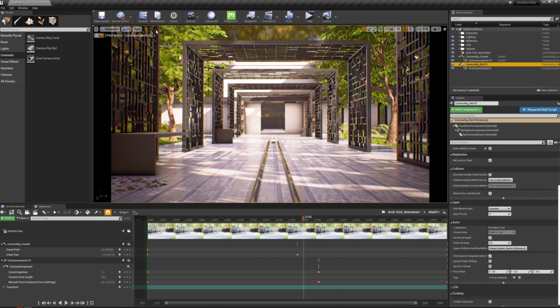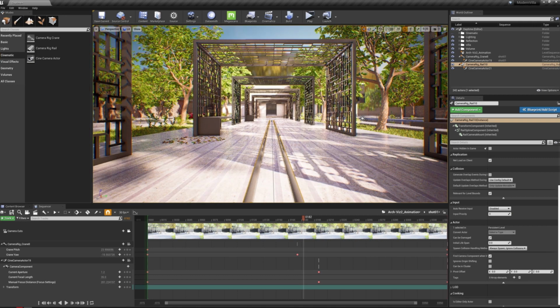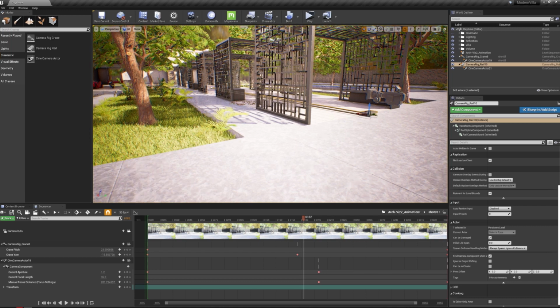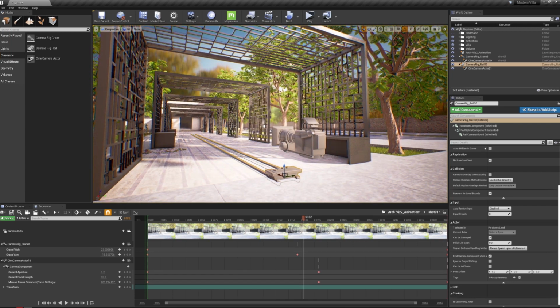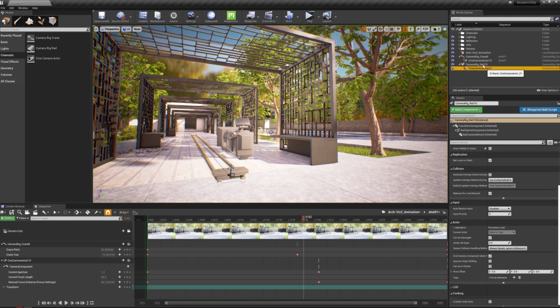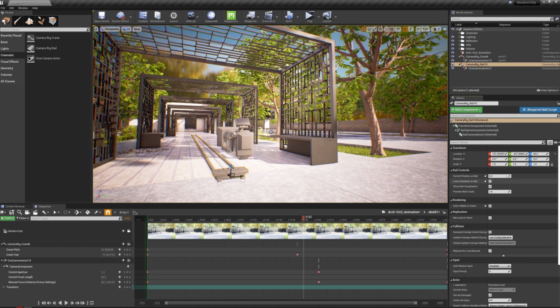So if we go back to our perspective outside the camera view, the rig rail movement is basically just one direction movements. If we go to the setting, you'll find the position is from 0 to 1. So I click, for example, 0.5. It's going to move to the middle of the rail destination according to how we set up the length of it, or to 1, for example, till the end. And let's start to set up animation at this part.